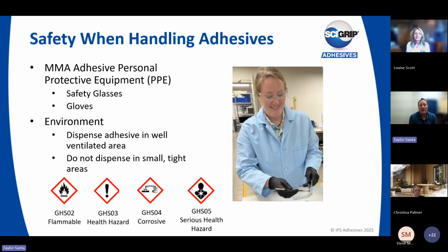So really, before we talk about any sort of specifications within adhesives, we want to think about the protective equipment and the safety measures that must be taken when using any type of adhesive. All adhesives are chemicals, and you should protect your eyes and skin from any potential contact with the material by wearing safety glasses and gloves. If contact is made with your skin, please wash with soap and warm water. If contact with the eyes occurs, rinse thoroughly for 15 minutes and seek medical attention.